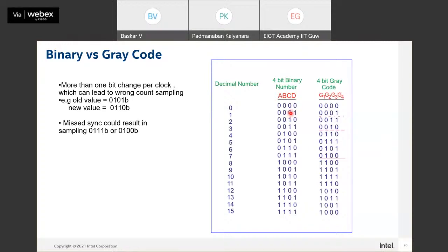Now this second location value 0 1 should be transferred to B domain so that B can compare against his value to check whether it is empty or full. Now while transferring, ideally the valid value that I transferred to B is 0 1. But what if B sees that as 1 0 or 1 1 or any other value? That means he is going to compare against a non-valid value, which could potentially cause functional failure. To avoid that, we use gray code.